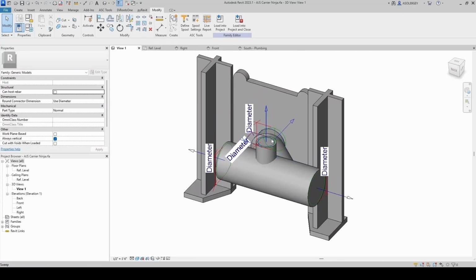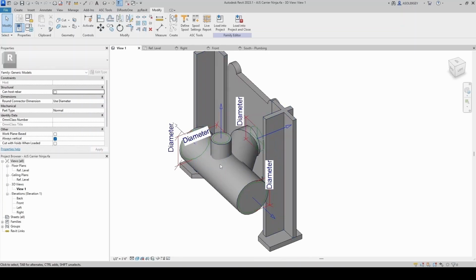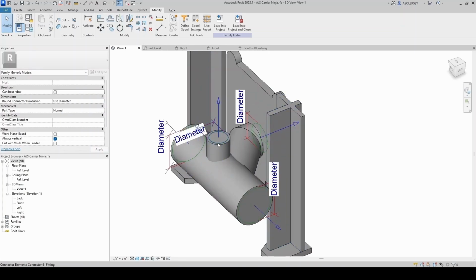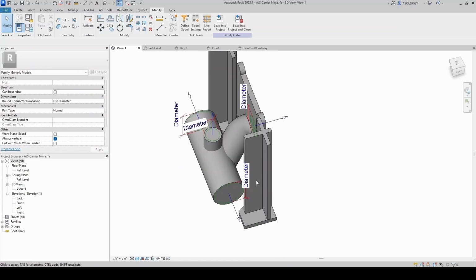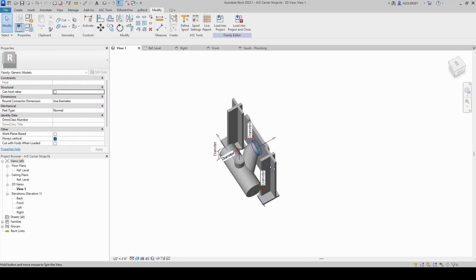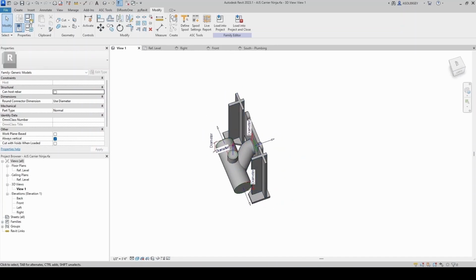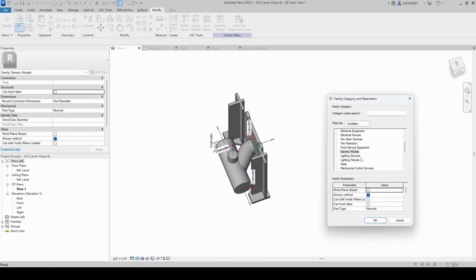Now, before I start joining any of this, I'm going to test my carrier first, and then I'll come back and probably join these solids a little bit. And now to finish this up, the most important thing. What's this? This is going to be a pipe fitting. You could define it as a multi-port, right? But I'd rather have it as a T, one in, one out, and one branch, and I ignore my vent. So I'm going to have this as a T, and I'm going to click OK.